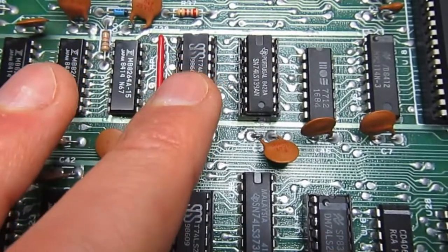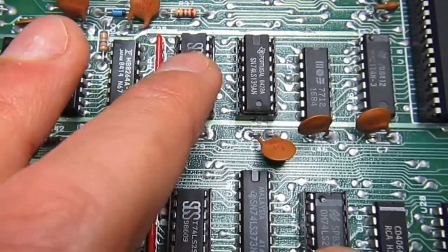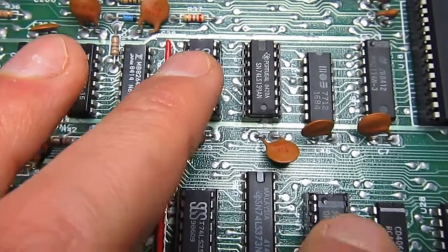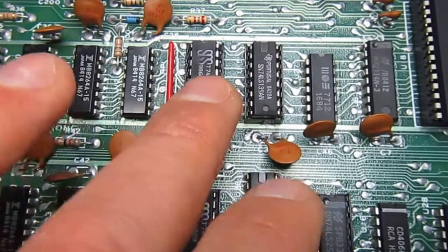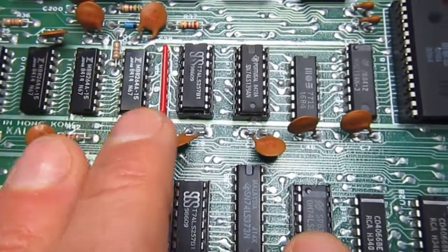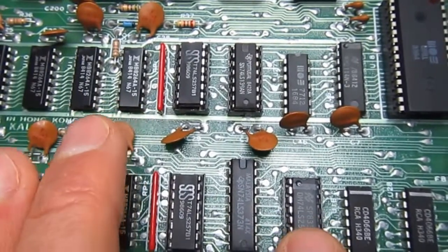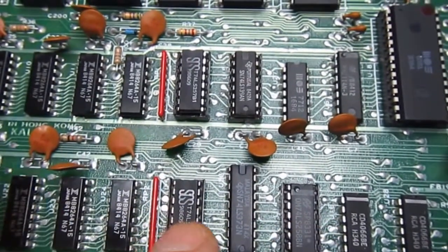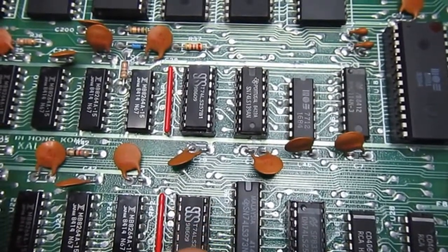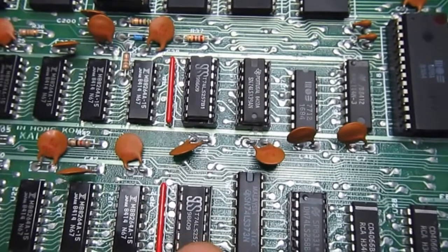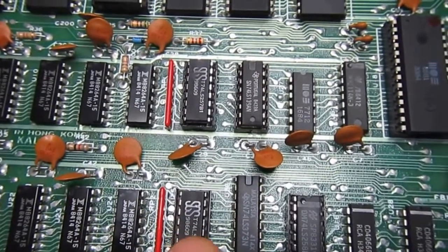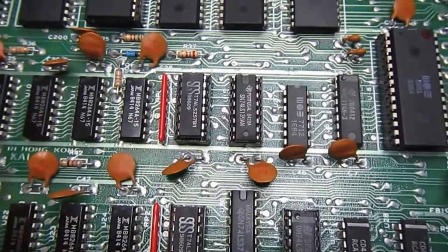to crash or go bad, because they drive the same address line but at different times. This one drives the line when the CPU wants to access RAM, and this one drives the address line when the VIC wants to access the RAM. This one had another kind of failure, so probably unrelated. It could have developed the failure even when the whole system was powered down.